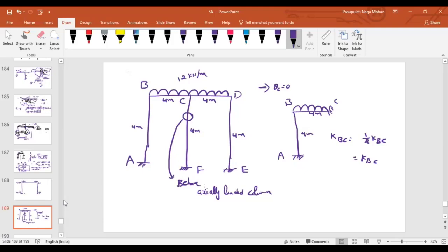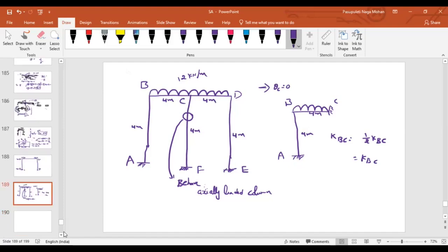By looking at the diagram, I can say AB is the shortest span, so for AB we'll have the larger effect, AB and AD. So AB is 0.67 and AD is 0.33. EI is the same, right? Moment of inertia is the same everywhere. Yes, sir. So obviously one length is 5 and another length is 2.5. So AD is 0.33 and AB is 0.67. That's it. Do you have doubts for that problem? No, sir, got it, sir. Yeah.